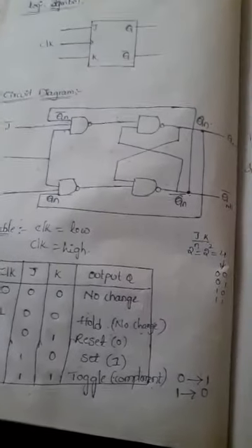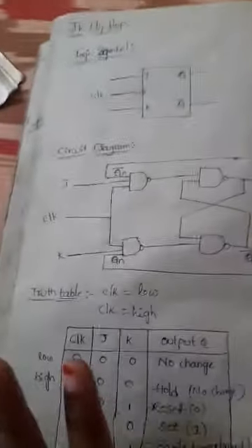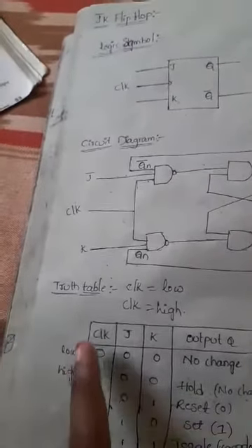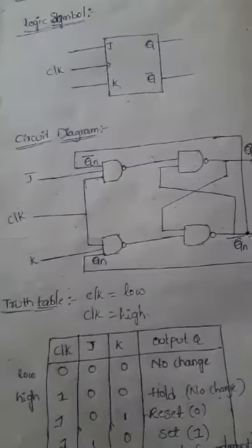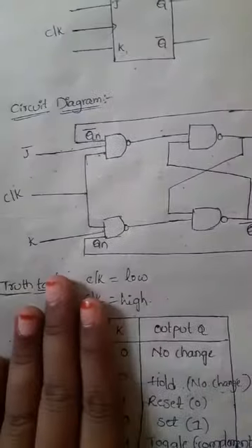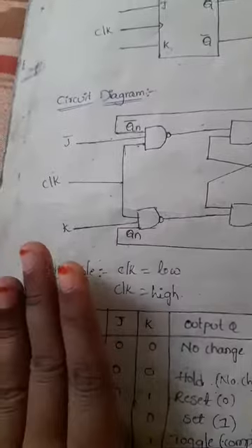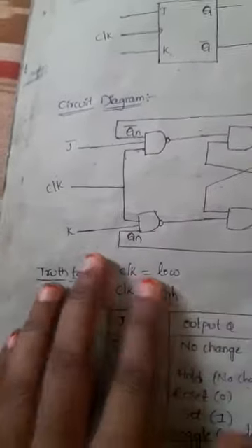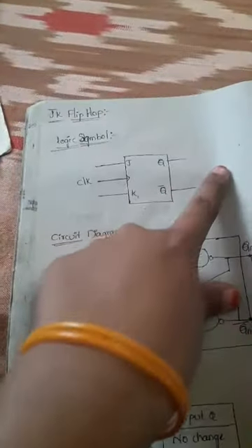In addition, one more flip-flop is the master slave JK flip-flop. The master slave JK flip-flop is equivalent to the normal JK flip-flop, but the difference is in the circuit. The master slave JK flip-flop is a combination of 2 flip-flops with a feedback connection from output to input path. That means we connect 2 JK flip-flops, and the output of the first flip-flop is connected to the input of the next one.